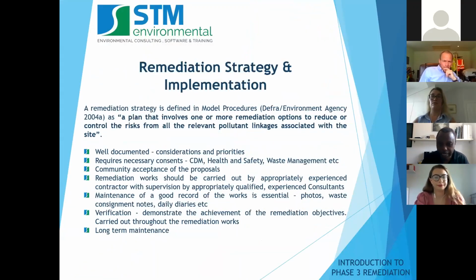I mentioned remediation strategies a little bit earlier. So you need to produce a report. Once you've worked out what you're going to do and how you're going to do it, produce the strategy, and send that into the local planning authority. And if they're happy with that, they will allow you to start the development. Typically, your strategy needs to detail the remedial works you're going to carry out, how you're going to verify that those works have been carried out, a very important part of it, timescales, etc.